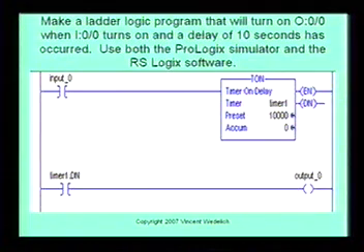First thing is out:0/0 is not a legitimate address scheme used in ControlLogix, right? That's an RSLogix 500 address scheme. So you know that you can type in your input or your output any way you want. So that's what I did. I said I:0/0 is input_0. And then we've learned in previous courses in RSLogix 5000, we can alias this to the slot 0, bit 0, and if it was in the local rack, we'd have local, and we've gone through that before, but we'll probably touch on that later as well.